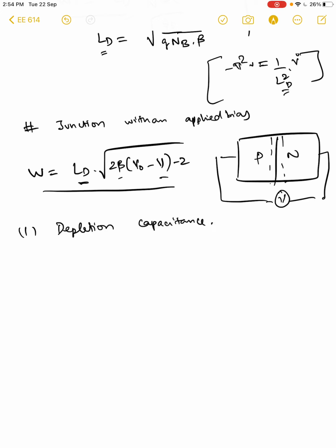Right. It's a capacitor because there is a region which does not have any mobile charge carriers, and it is engulfed by regions which have very high charge density in comparison. So basically this is an equivalent of a metal-insulator-metal junction, which is a capacitor for all practical purposes, right? So this particular structure also has a capacitance.